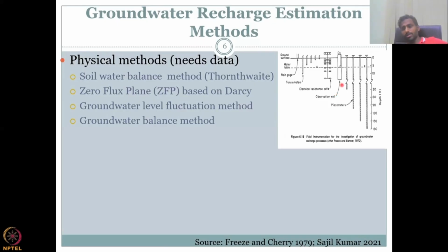Then you have observation wells, which are wells with a meter in them, and piezometers, which are deep aquifer wells. So these two are just wells, but the difference is the depth. You can see here how deep it is. It is a broken y-axis, so it is not going in tens and hundreds. It goes in different units, okay, depth in feet.